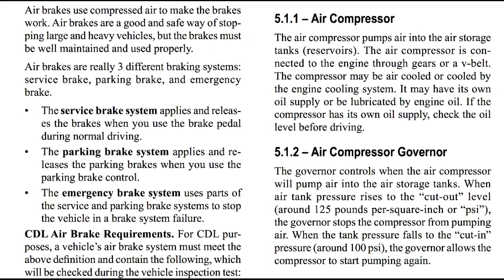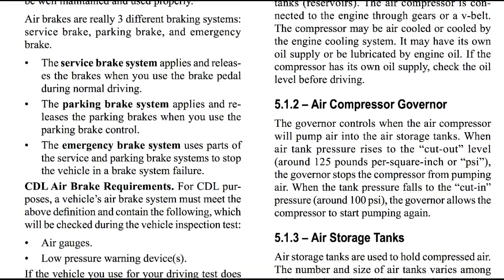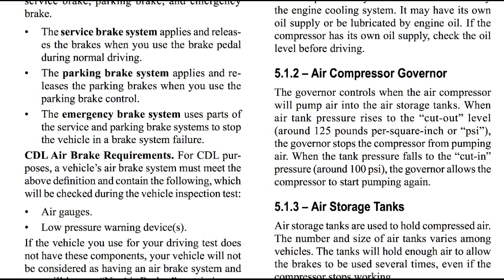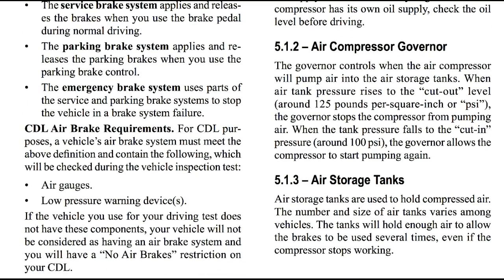Air brakes are a good and safe way of stopping large and heavy vehicles, but the air brakes must be well maintained and used properly. Air brakes are really 3 different braking systems: service brake, parking brake, and emergency brake. The service brake system applies and releases the brakes when you use the brake pedal during normal driving. The parking brake system applies and releases the parking brakes when you use the parking brake control. And your emergency brake system uses parts of the service and parking brake systems to stop the vehicle in a brake system failure.